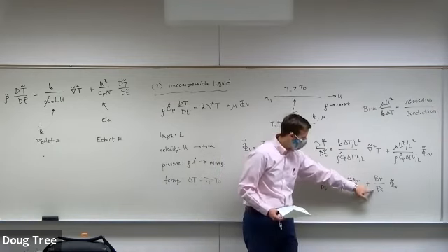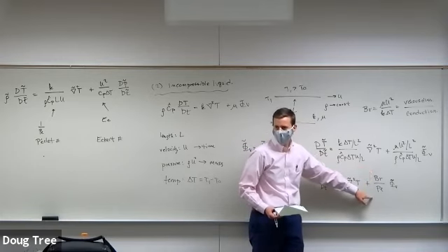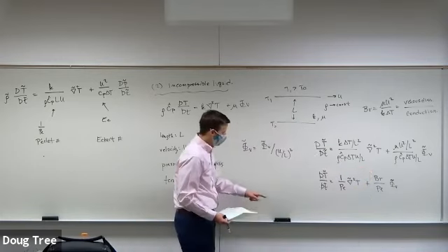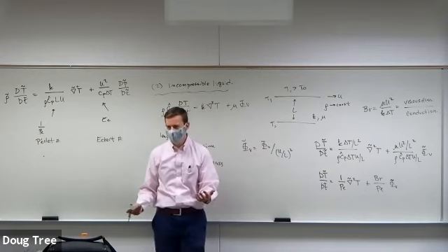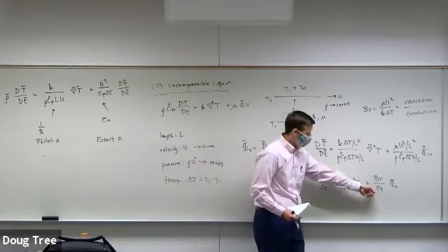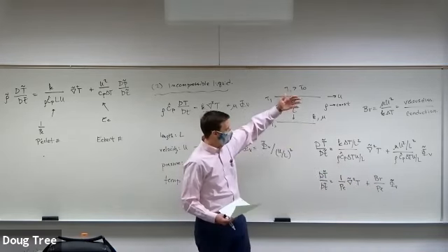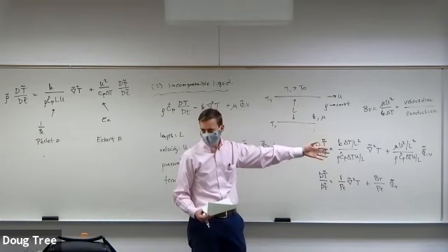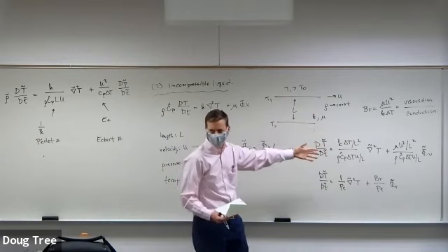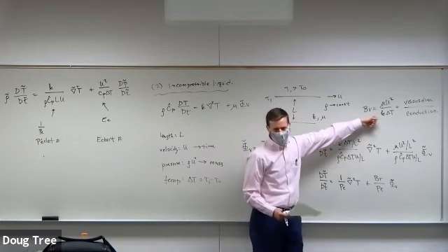So when we divide them, we get viscous dissipation by convection. And it's just a convention of how the Brinkman number is defined. So that's why we write it as Brinkman divided by Peclet instead of whatever other number was there. That means viscous dissipation divided by convection. Does that make sense? So now this is the answer to Andrew's question.